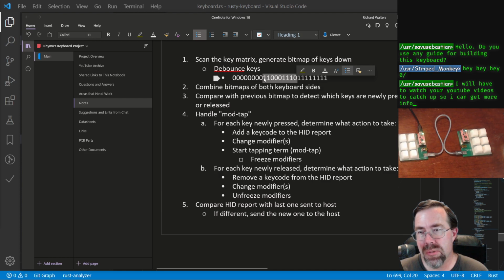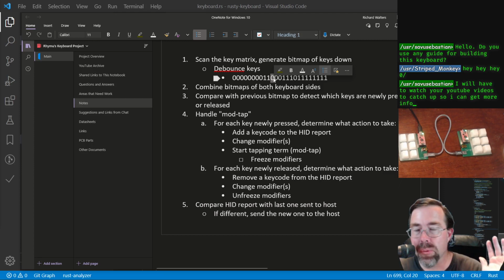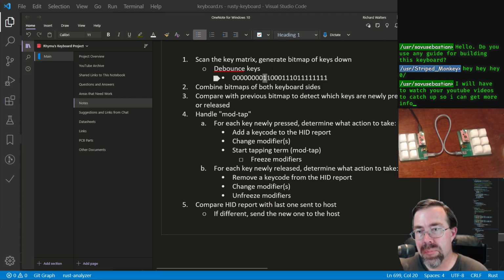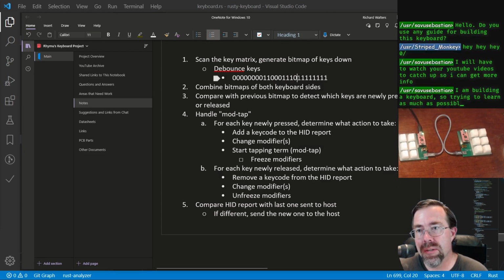So what I was planning to do is whenever we see a 1, we'll start a countdown. And if we see a 0 before the countdown is done, then we'll just ignore that. So start counting, stop counting, because that was spurious, right? And then start counting again, stop counting, and then start counting again.